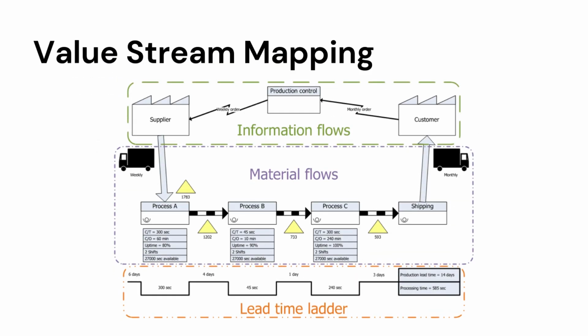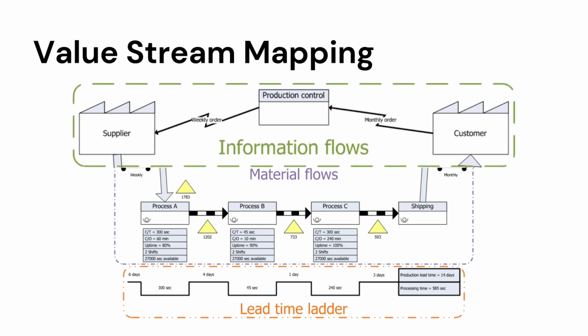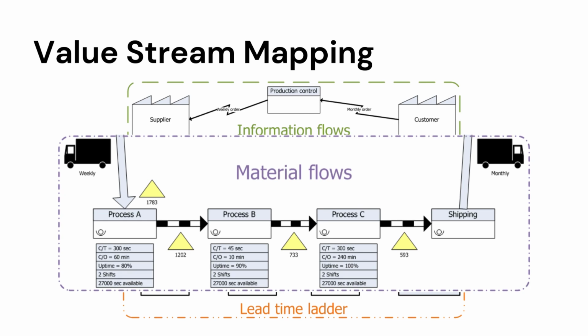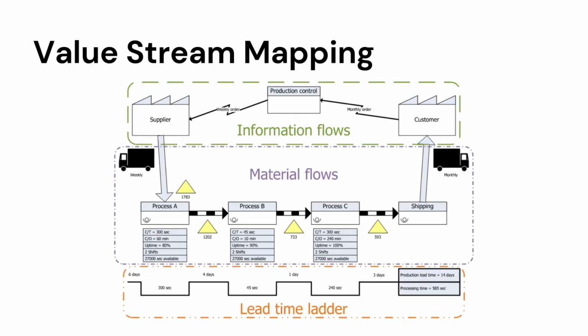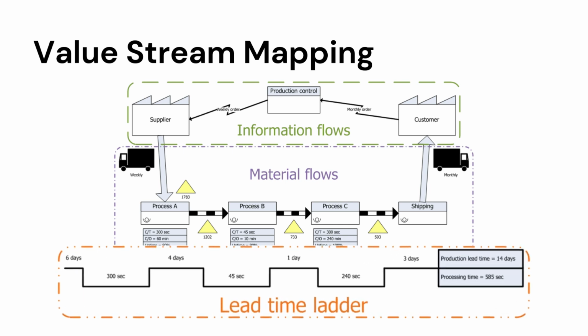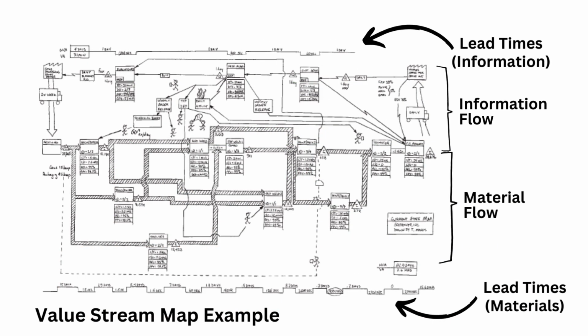Value stream mapping is a lean manufacturing tool used to visualize the flow of materials and information in the production and distribution process. A VSM displays all critical processes, beginning with the first step in manufacturing and ending when the product reaches the customer. A basic VSM is a flowchart loop where the information flows counterclockwise from customer to supplier across the top, and material flows from supplier to customer across the bottom. Paired with the material and information flows are the lead times for each process. Real VSMs are often a lot more complicated, containing several interacting or overlapping processes.